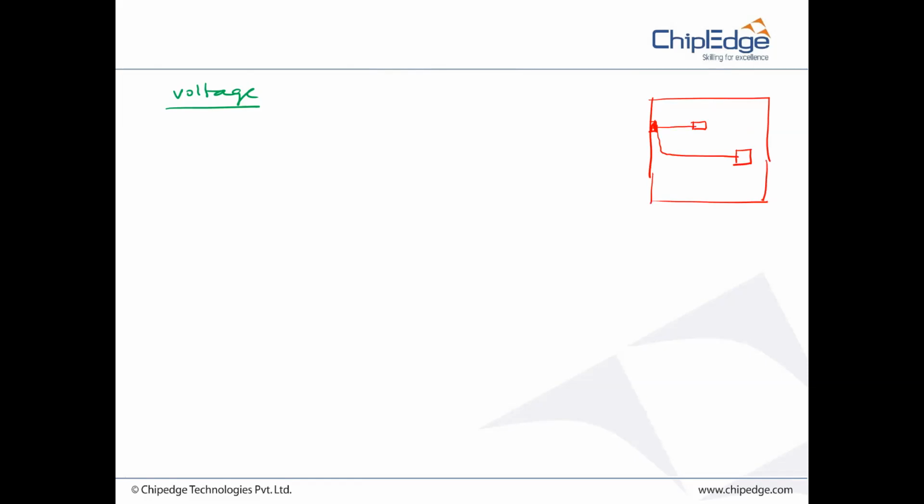Now, sir, for example, think that this is your supply voltage, Vs. You are giving supply voltage to this AND cell or anything, macro, whatever it may be, standard cells. So is the voltage reaching this first cell and the second cell the same? No, sir. No, it will be different. Why is it different? That is what is known as your corners.